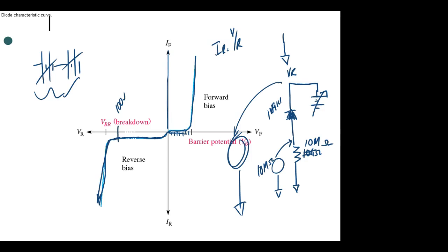Why? Because my meter is in parallel with that 10 megohm resistor. Now, normally, let's say I have a 1K resistor and I want to measure the voltage drop across that 1K. And that meter's got 10 megohms. That 10 megohms, we're going to forget it completely, right? You understand? But if I get into a high resistance circuit with a meter, we cannot ignore the resistance of the meter.